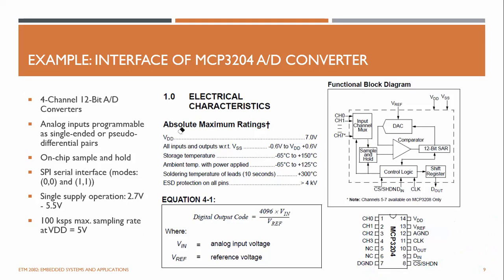And this device will output digital data, which is the ADC sample data. That binary data is given by this equation: 4096 times Vin, where Vin is whatever voltage you apply to the ADC channel, divided by the reference voltage, the reference voltage that you provide to the device. Depending upon that, you can get the binary value of the ADC readings from here.